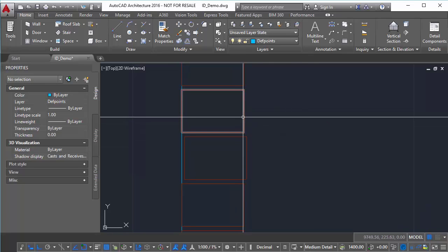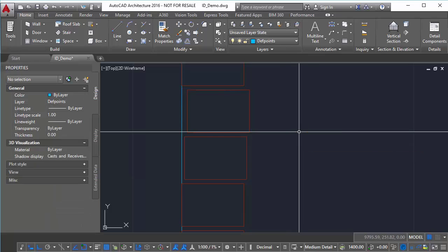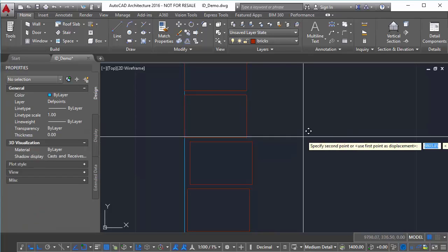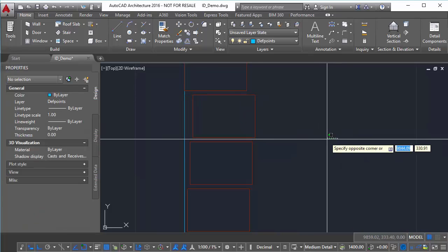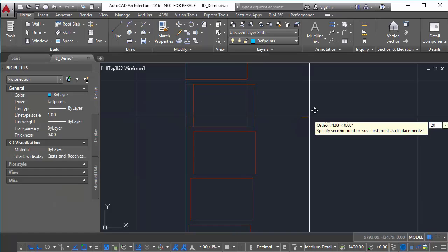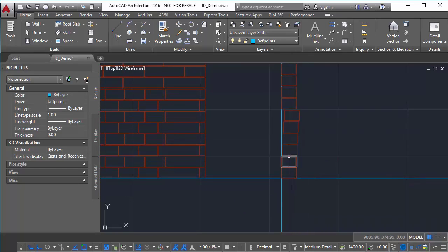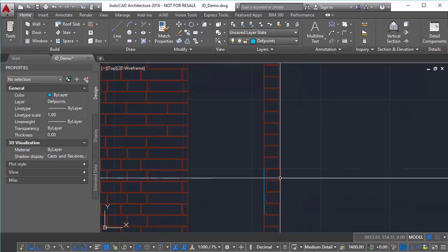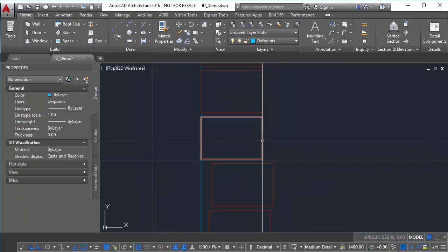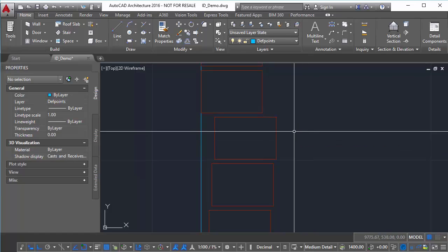All right, so if I move that one 5, I'll have to move this one 10. So what I'm doing is making a subtle shift in the movement of the wall, just by starting to alter these little by little. I'm adding a 5 millimeter shift in this case for each one. I'm starting to play with that pushing and pulling to get a pattern, and we still are concentrating on this subtlety, this gradient pattern that allows us to get a smooth reading.